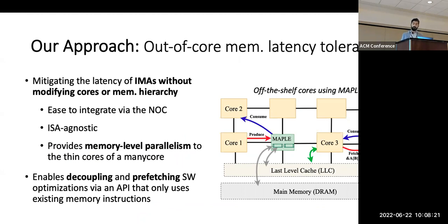And in order to enable practical adoption of latency tolerance in many core SoC designs, we proposed Maple as a memory access parallel load engine, a mechanism that implements decoupling of access and execute phases of an application, and a specialized programmable prefetching in this piece of hardware that is outside the core and connected to the network on chip.